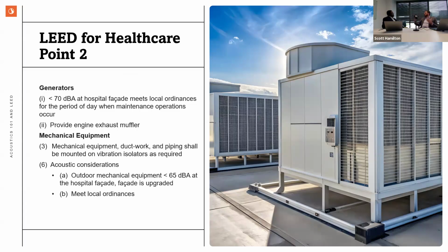And so that kind of stuck the project, where I think it was acoustic finishes you were stuck on. And it was a clean room environment. So perforated materials don't work in a clean room environment. So there's a reason to go for a variance on that space, especially if there are no acoustical considerations or communication happening in that space. So under LEED v5, that space actually might be a more approachable solution. Yes, that's a great point.